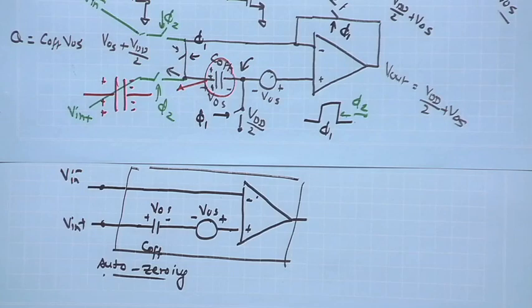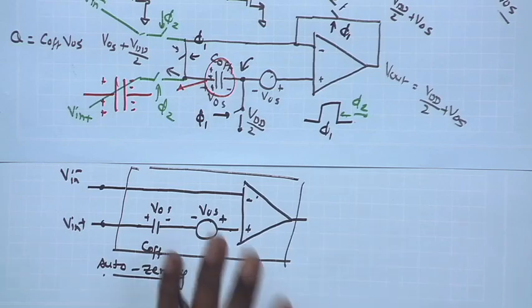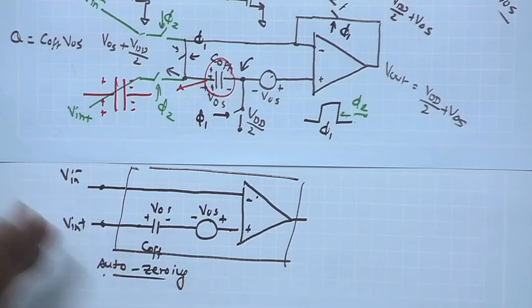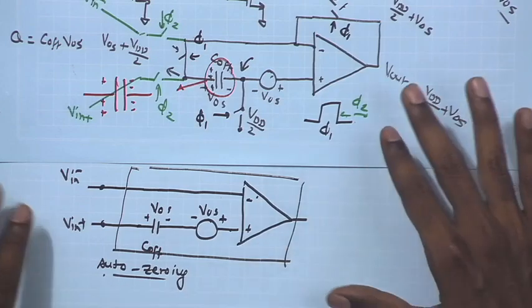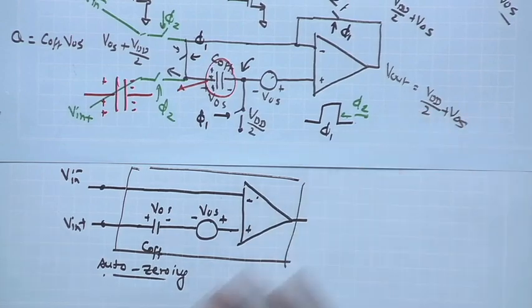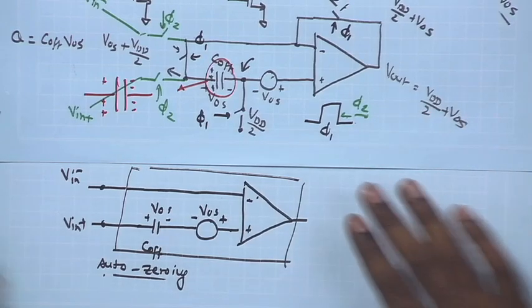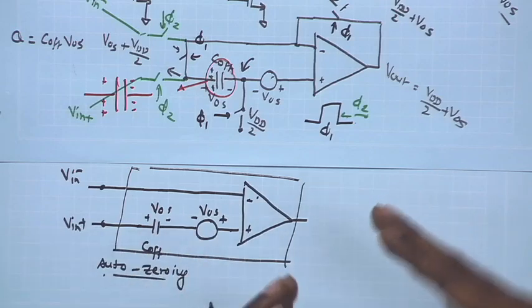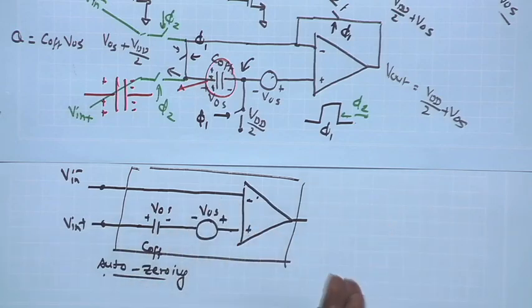Even the front end amplifiers may have offsets, and in certain cases cancellation of those offsets can also become important. Right now, so far we have not discussed the issues related to offset of the front end amplifier. We will see there the concerns are significantly different, and we will see what techniques can be used over there to mitigate the offsets, and whether it is an equally important concern over there. Here we have discussed with respect to the comparator what is the effect of offset, what is the effect on overall comparator performance, and also the ADC characteristics.